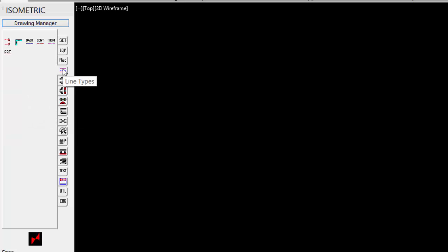Under the Line Types tab, we see our pipe routing line, our border line, and some basic lines like dashed lines, center lines, and hidden lines. The Auto Route feature allows us to enable and disable the auto route, as well as see the current position and undo the last item. Under the Flange tab, all of our basic flanges are shown, from weld neck flange to the flange complete with gasket and bolts, to a flange set, to pipe nozzles, API flanges.